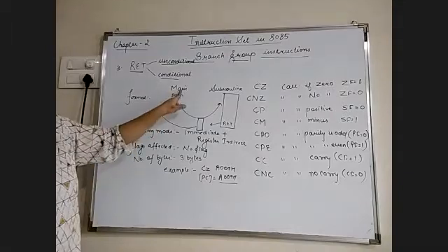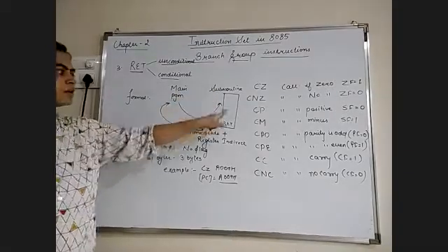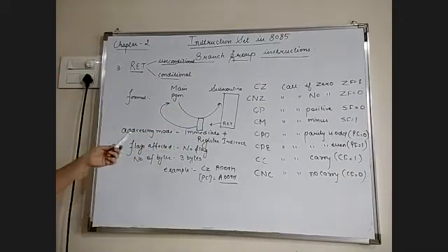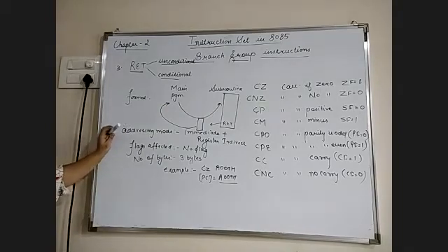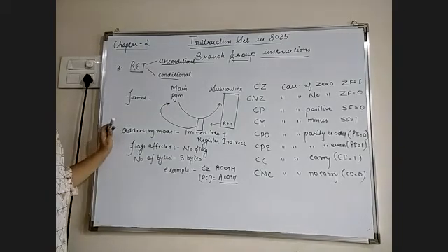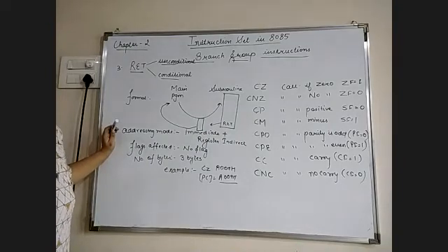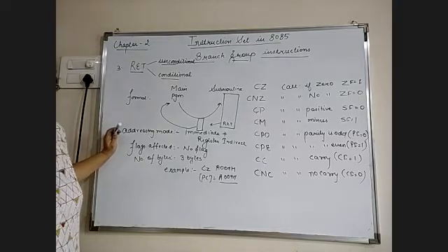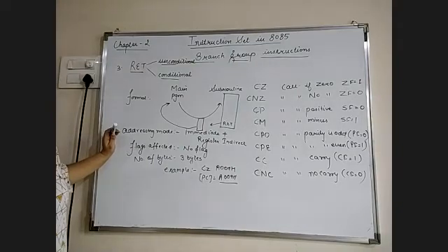Okay, so call will move from the main program to the subroutine, and return will come back from the subroutine program to the main program. So when this instruction is executed, the program counter is transferred from the subroutine to the calling program, or we can say from the subroutine program to the main program. The return address is popped out, or taken out, from the stack memory. That means the contents of the return address will be popped out from the stack memory.